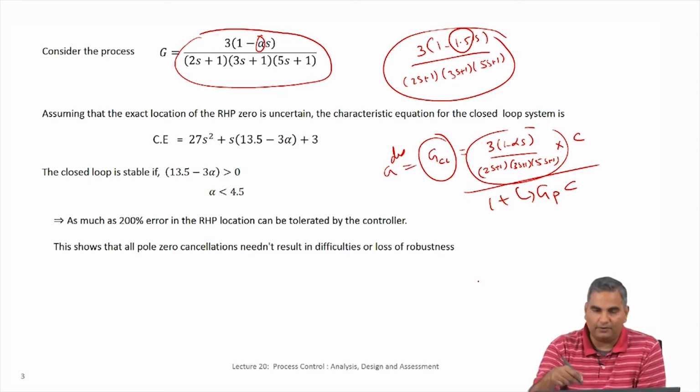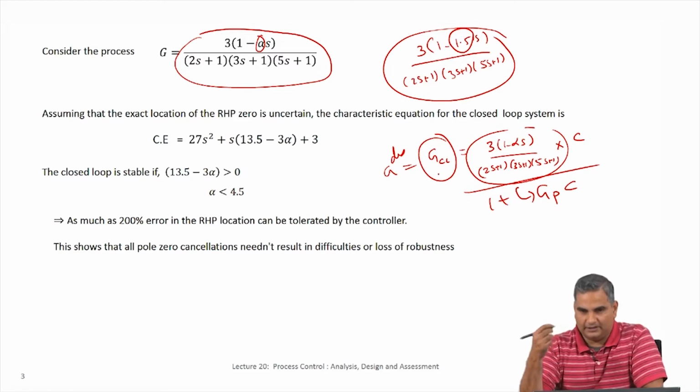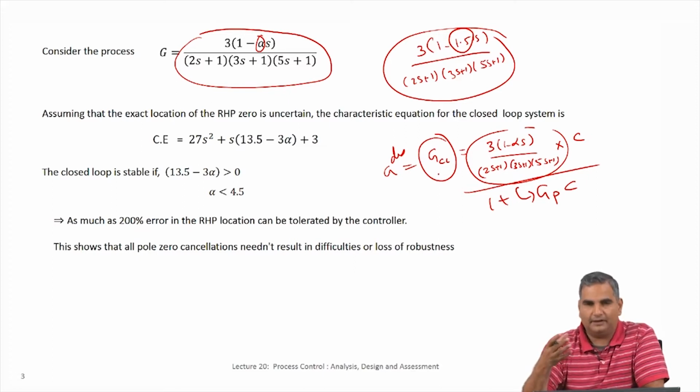Okay. So, the loss in performance is already there, which is the difference between G closed loop and G desired in some sense. So, performance loss because of model plant mismatch is okay, but I do not want the system to become unstable because of this plant model mismatch. So, I should also judge whether there is a possibility of that happening.